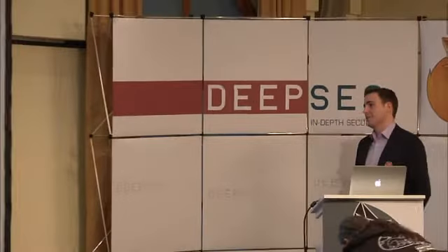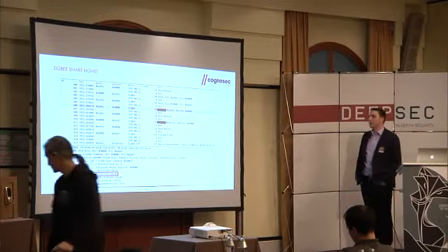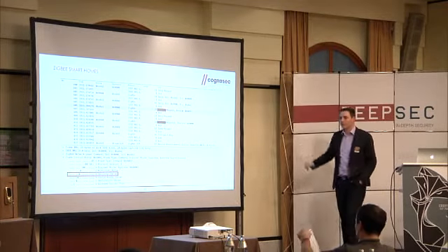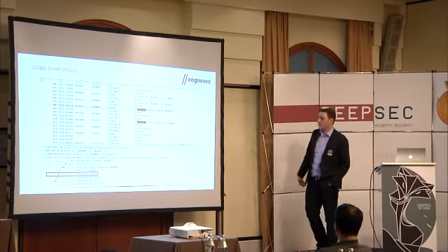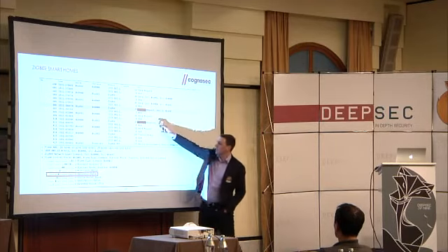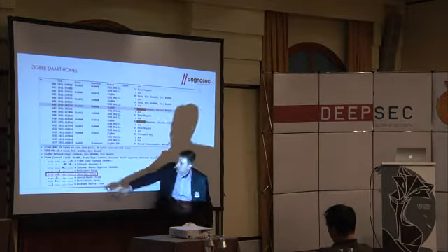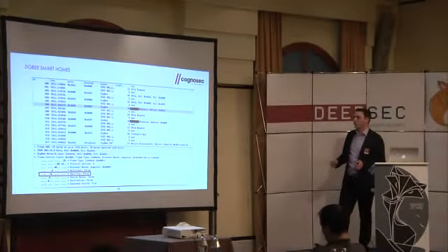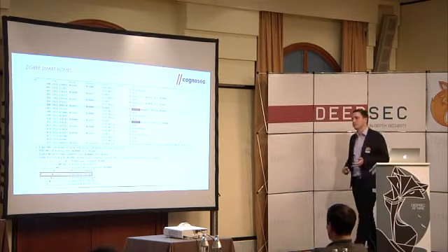So what we would have seen is that there is a special command called rejoin. If a device is able to rejoin the network using a non-secured request called insecure rejoin, that's actually a Wireshark output. So this is the rejoin request, and you get the rejoin response. What's interesting at the rejoin request is that the security level is set to false. This means you need no secret data.